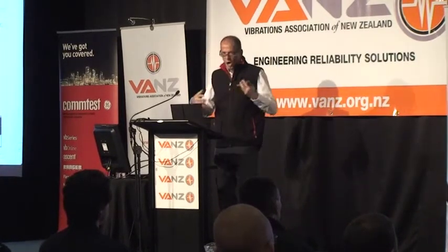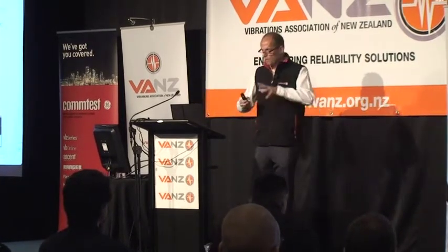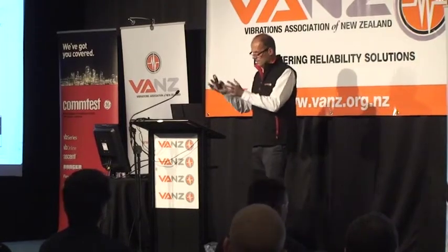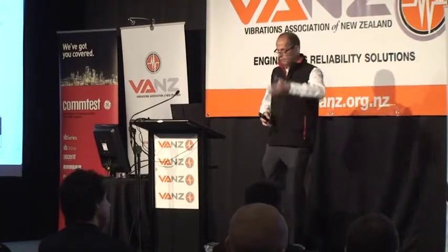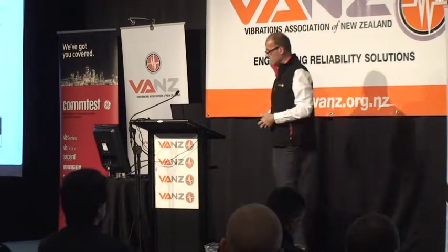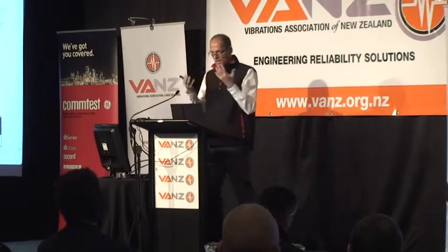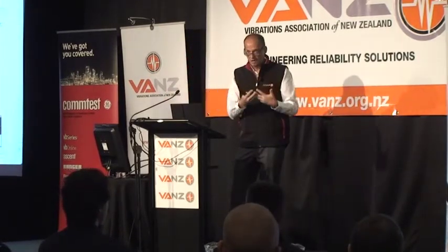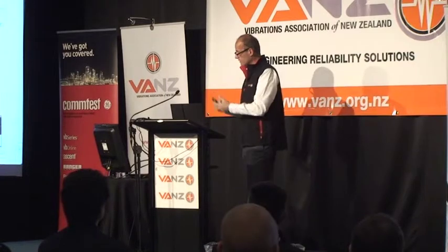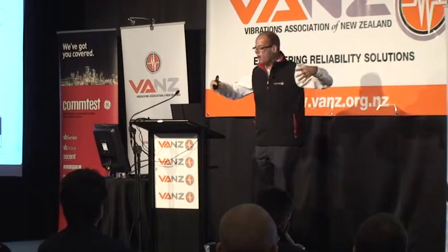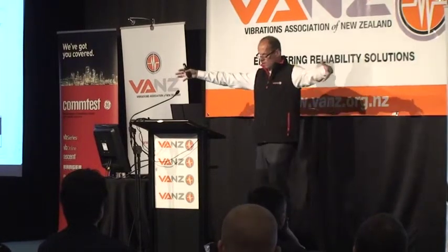Phase helps me understand the motion. So the spectrum split out all the frequencies. You know, there's the 1x peak and the 10x because I've got 10 blades on the fan and so on. So that's good. Time waveform shows me the nasty things that are happening, the impacting in the bearings when the bearings are damaged, the impact on the gears. But from a vibration analysis point of view, it's often very helpful to understand the machine as a whole.